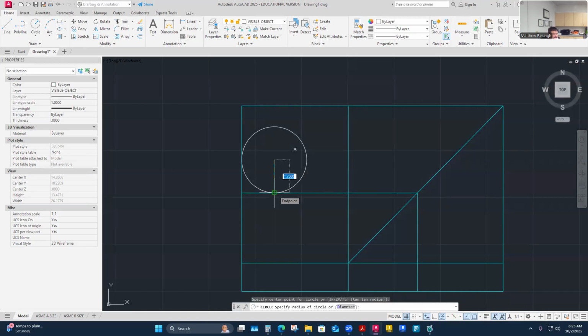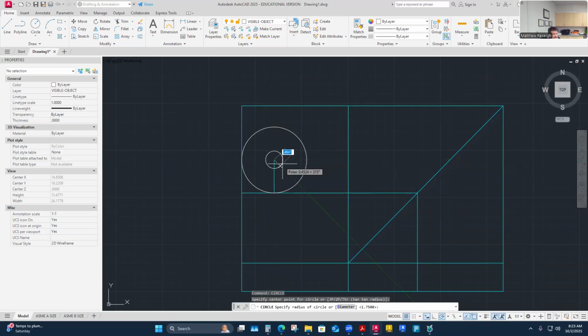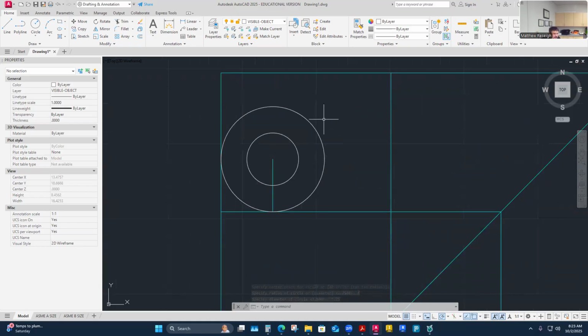This is the outer one, 1 3/4 inch radius. And then I have a diameter of 1 3/4. So I could go D for diameter, D enter, or D spacebar, just like you said. And this is 1 3/4. So it's a start. And then it's just going to come here. I think there's a radius out to this leg here, and then it goes all the way, and then it has a little miter here.